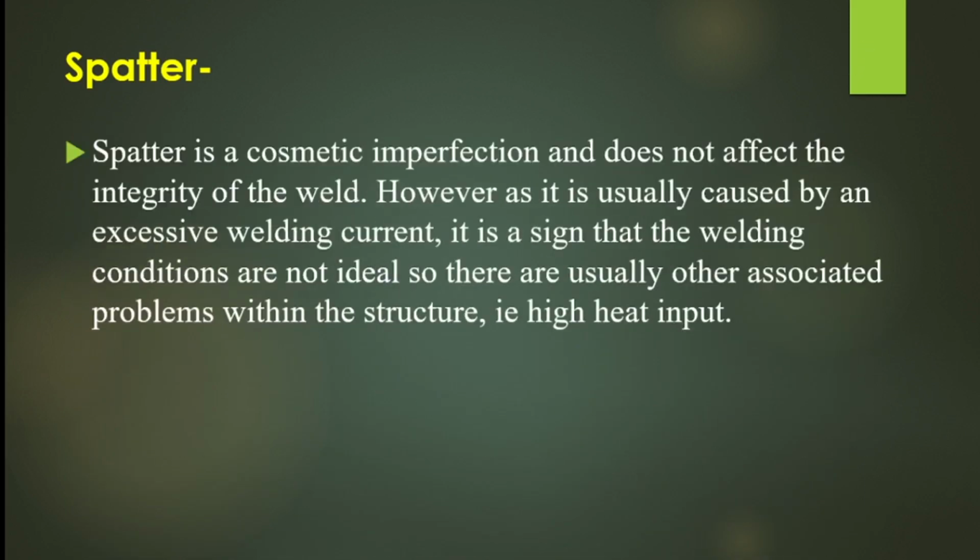Then we need to take note that spatter is a cosmetic imperfection and does not affect the integrity of the weld. However, it is usually caused by an excessive welding current, and it is a sign the welding condition is not ideal and suitable. So there are usually other associated problems within the structure and high heat input.